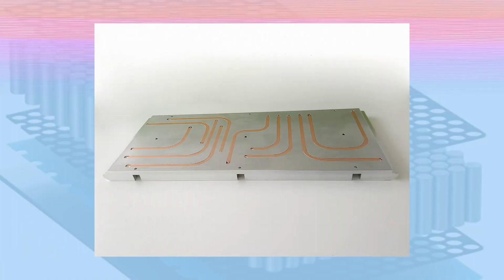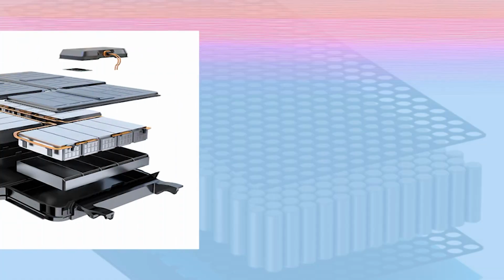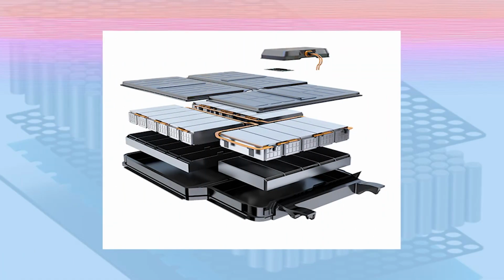The heat sink case design depends first on the amount of heat being produced. You have certain calculations that will tell you how much heat is being dissipated at peak power, given the ambient temperature and the current flowing through the converter. Based on that you should select the volume of the heat sink. When the volume is selected, we must ensure that the volume of the heat sink and the size of your converter match each other.